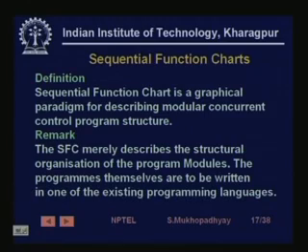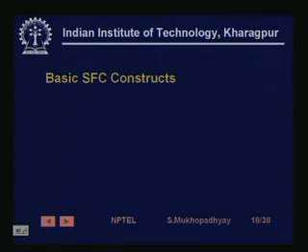So you have this remark which says that the SFC merely describes the structural organization of the program modules, while the actual program statements in the modules still have to be written, probably using existing PLC programming languages, either RLL or instruction list or whatever. Let's take a quick look at the basic SFC constructs.